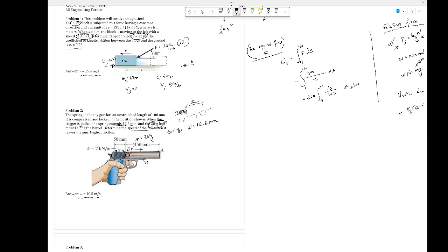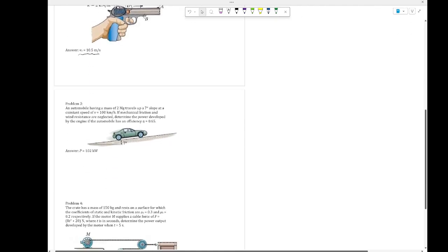So bottom line, here you have the spring force exerted on the projectile. So you are saying spring energy, half k x squared, everything is given, equals half m v squared, where half m is known and v is the unknown. That's what I'm saying, this is a super easy problem. I really don't want to write even the equation here, because if I write the equation, I'm giving you the solution anyway. Any question, Joe? You can deal with that, right? Easy peasy. All right, moving on.